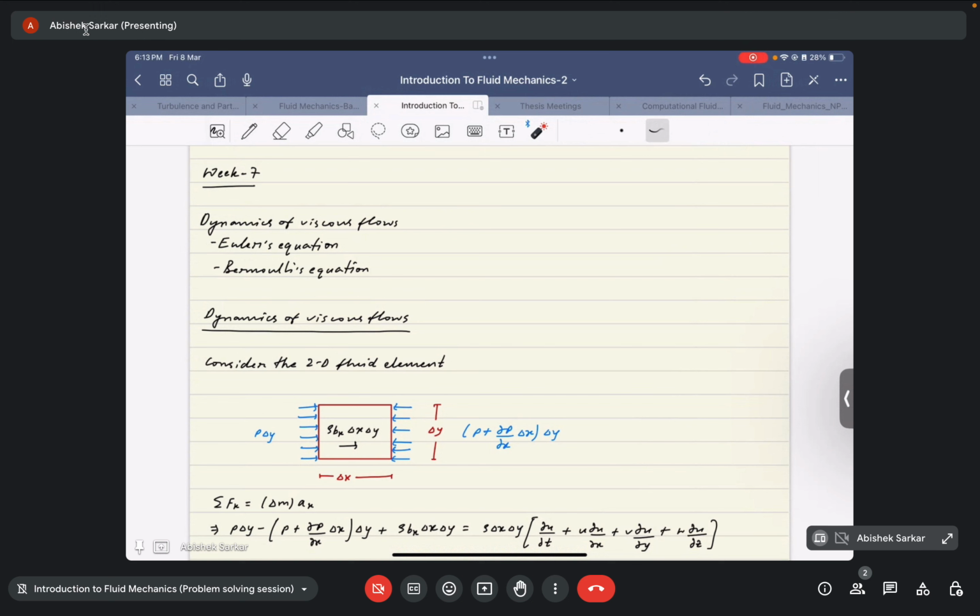I mentioned that the driving factor in boundary layer flow is the inertia of the incoming flow, and in the case of flow in a pipe, it is the pressure gradient that exists between the two ends of the pipe, right? Those are considered to be driving forces, meaning the forces that act upon the fluid that generate its motion, or that cause the fluid to flow.